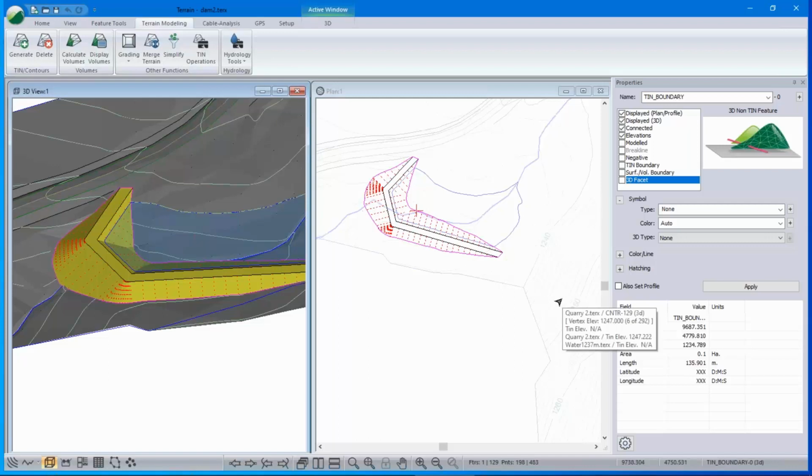Very good. And another question here, just in terms of maximums. The next question is there a maximum number of lidar points that I'm able to import? If you bring in more than 10 million, you might be asking for trouble. So we generally say keep your surface data points to be under 10 million. That said, if you have a really powerful computer, you might be able to go higher than that. And as computers get faster and memory gets bigger and so on, maybe that number will change. But 10 million is a reasonable number at this point.